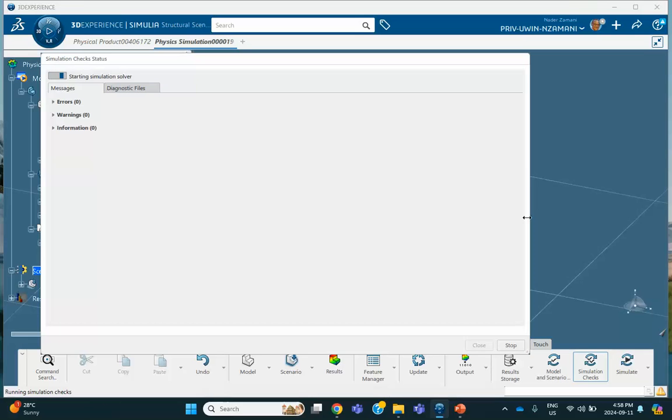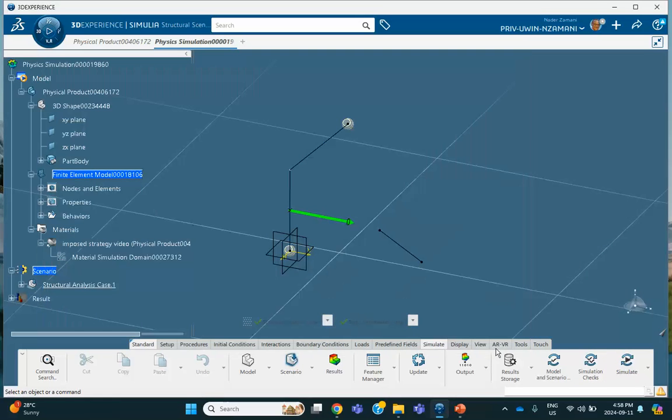Made a difference here is that extra geometrical feature, the line that I created, I didn't use it. It's just that without that, it would not allow me to basically include that point that I created in my finite element model. So this is fine. And then once I get the close box here, I close it and then simulate. Okay, good, close. And now we're gonna run it.